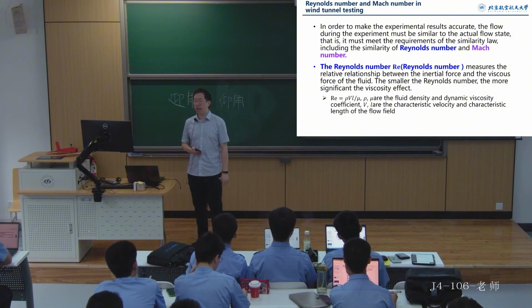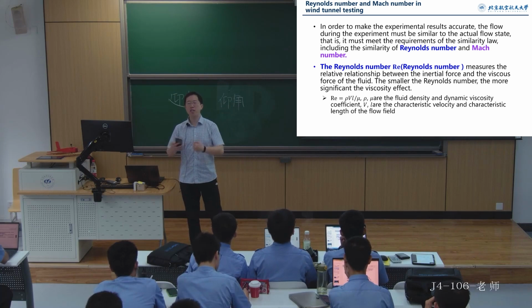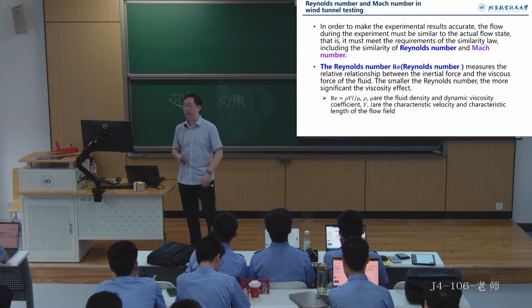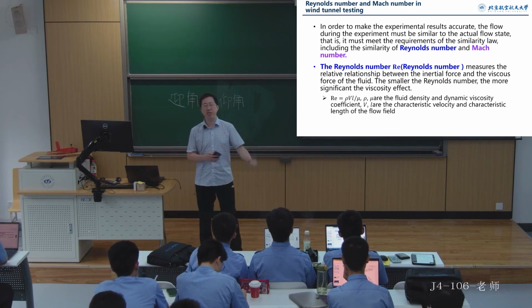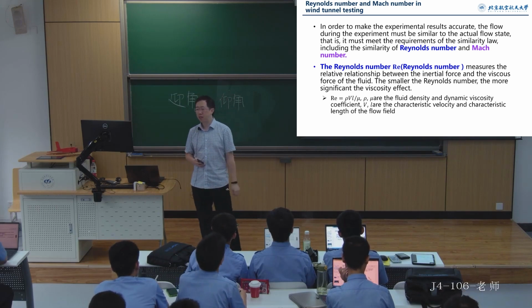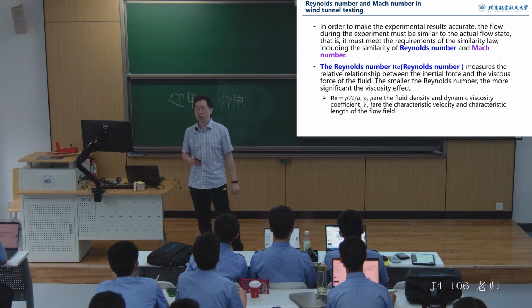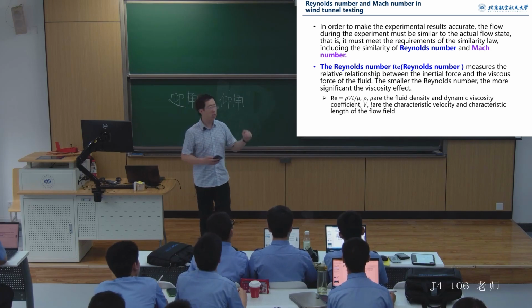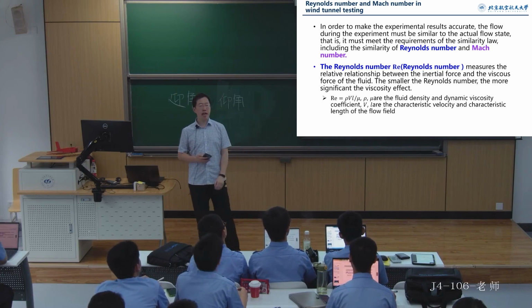number. But if we throw this aircraft into a pool, water, as we mentioned before, is also a fluid, right? It has similar properties to air. So, at this time, how does the force exerted by the viscosity of water on the aircraft compare to the aircraft's inertia? Is the magnitude compared to before? It's more similar now, isn't it? At this point, it is in a state of low Reynolds number.